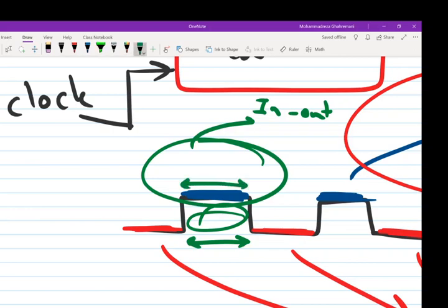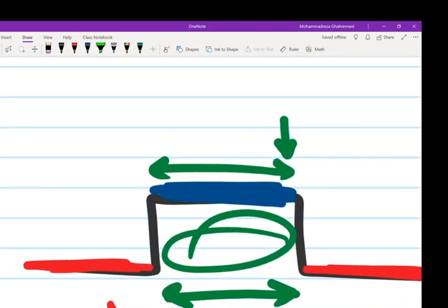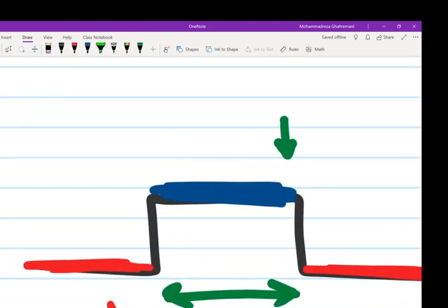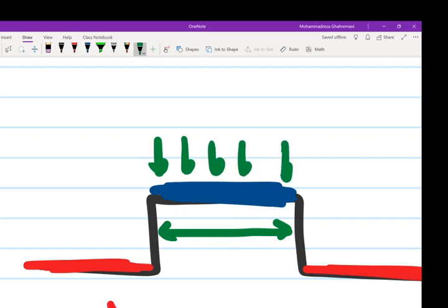So the last value of the input in the active level, which is right before the transition, is exactly here. Let me zoom in and show you. I said that during this time, from here to here, any changes in the input will be transferred to the output. Let's say we have one change here, one here, one here, one here, and one here. So change number 1, 2, 3, 4, 5.